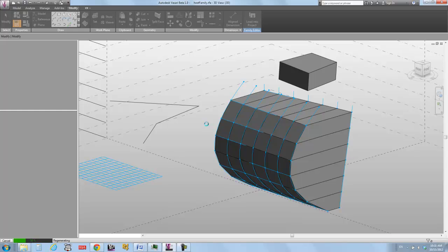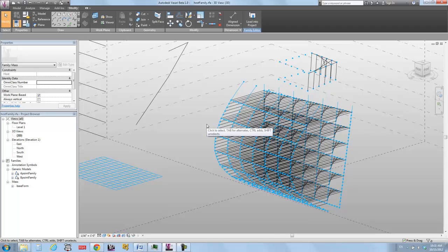And now this is where you're going to start seeing a lot of overhead and performance issues from having a lot more geometry and a lot more relationships to regenerate. And this is where you can start seeing the payoff for separating out the larger building form from the components. Because if you wanted to go in and manipulate that building envelope, it would be kind of a drag to have it regenerate every time, right? So does everybody have some sort of goofy pinhead geometry happening here?